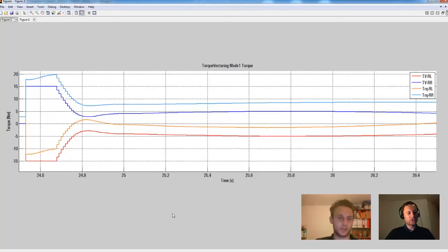Let me ask a question at that point. Right before timestamp 24, we see a step function. Where does it come from? Is it a driver input or a controller response? What do we see here? Yeah, for sure, that is the driver input. The driver is performing a step steer. This part of the optimization is used to optimize the response time of the controller.